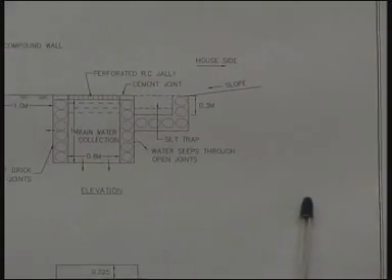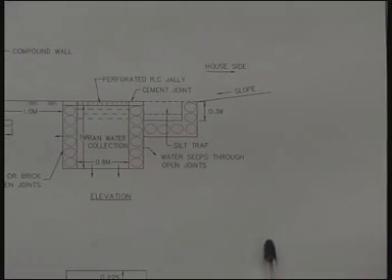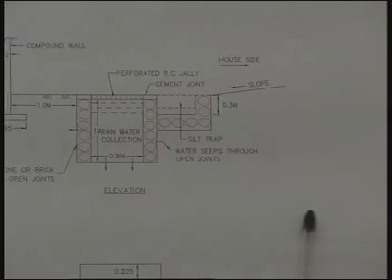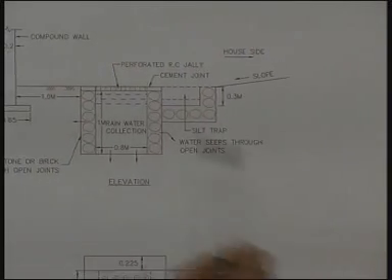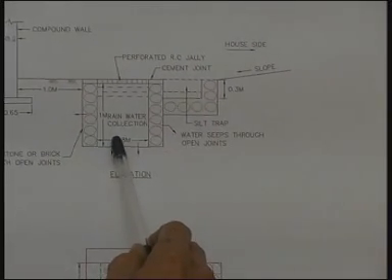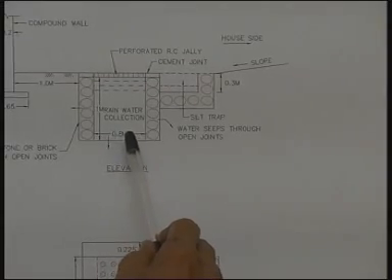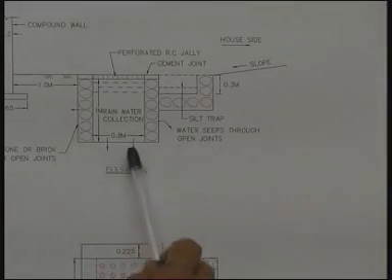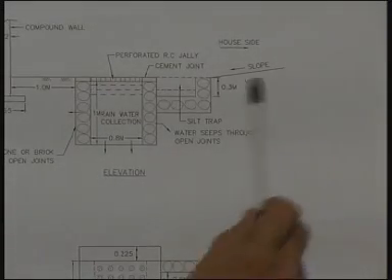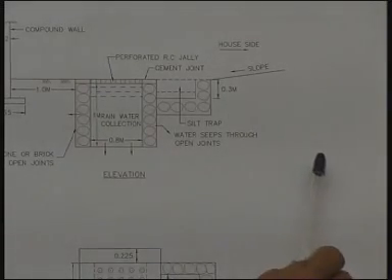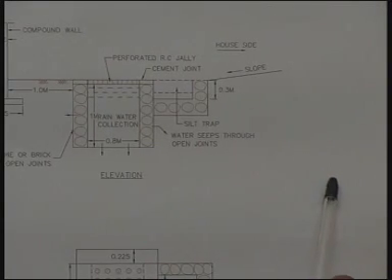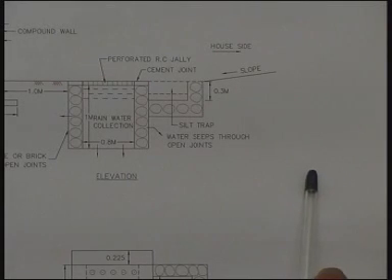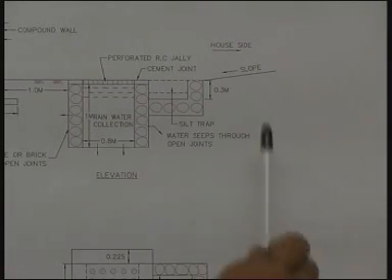The foundations of the column should not have any cavity within that bulb of pressure zone, what we call the bulb of pressure zone. Now this cavity is not in the bulb of pressure zone of the foundation, it is away from the foundation and it is at a higher level than the foundation level. So there is no problem of interfering with the foundations and causing instability with regard to the structural details of the foundation.